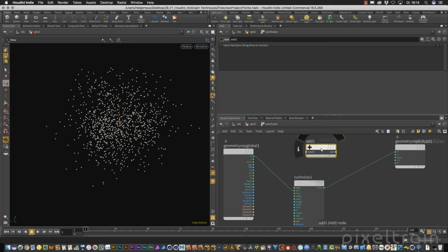But one thing is important. You see that the ports in the moment are white. White means neutral. They are not really set to which data type they have. And this is really nice. These arithmetic nodes inside of Wax look into the first input they get to change the way they work. For example, if I take here the position now, which is a vector, and add the vector here to this input 1, you see now the output is also a vector. And so it's important that you decide which data type you need.